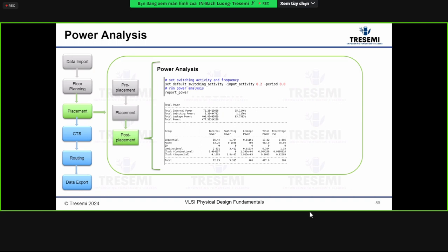in general, you go and do the timing analysis. You try to meet timing. Timing closure is the most challenging, and you do power as a side optimization, because if your timing is not met, then the chip is not operational. Power is being saved and optimized because it impacts your performance, right? Your chip performance.